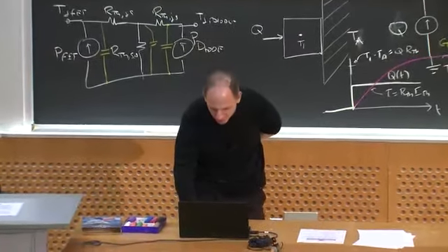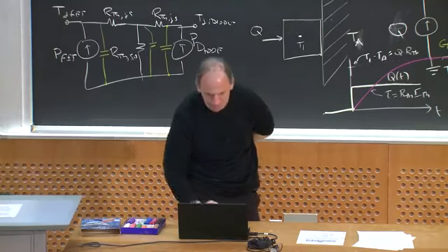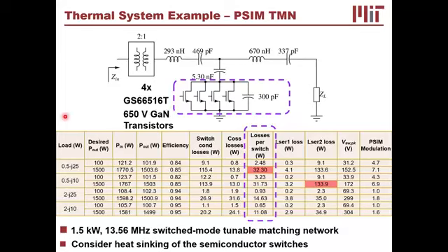The last thing I wanted to do for you today is show you a thermal transfer example. Here's what I'm going to show you. This is for a particular matching network design that we did, and it has 4 transistors mounted between the circuit and ground. Each of these transistors can dissipate something like 30 watts in the worst case. High power design. So 4 devices times 30 watts is roughly 130 to 140 watts. That's a lot of heat to pull out of these little devices.